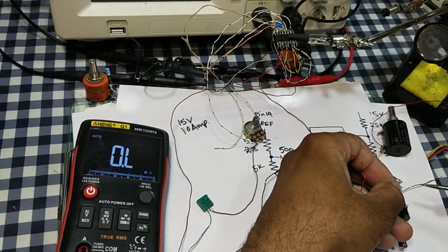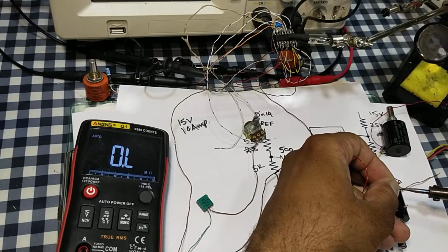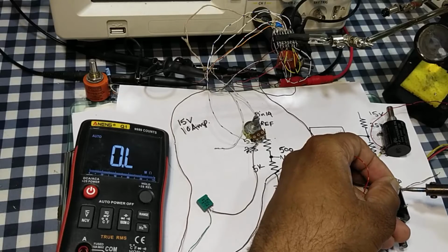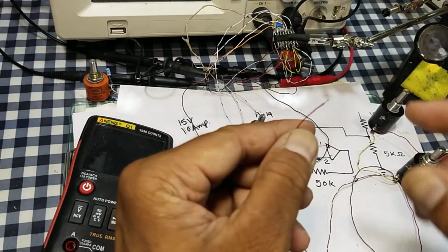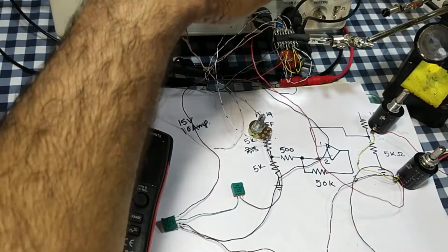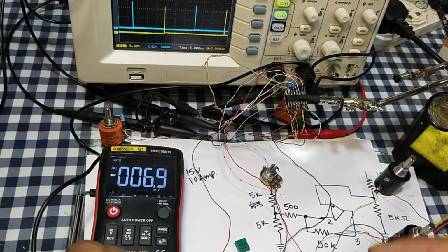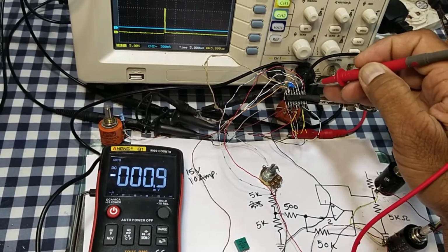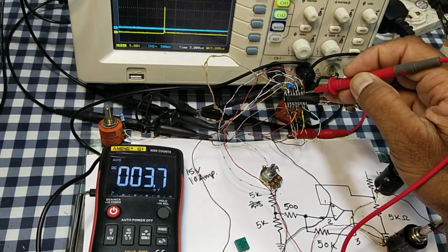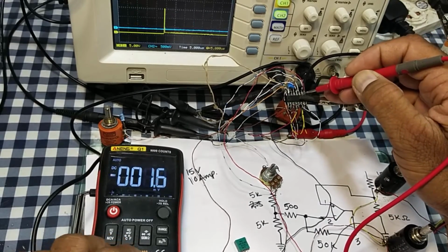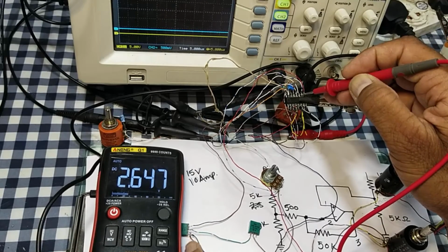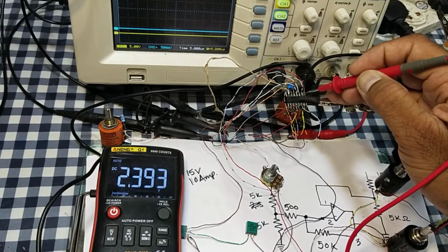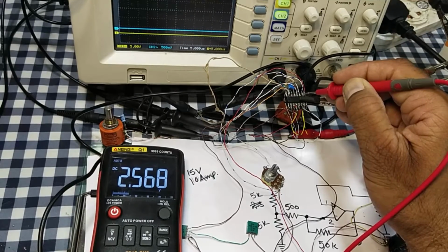Basically, it is the output pin of any power supply. This time I am simulating this voltage. This will go to pin number 1 of this IC. This time we programmed pin number 1 and 2. Here we have pin number 2, to which we applied a reference voltage, and we have feedback voltage 2.5 volt.